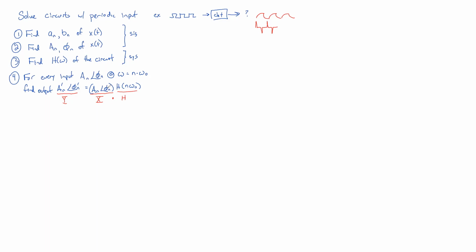So this is going to be a complex number. This will be a complex number. Multiply them together, we'll get a complex phasor output. And now that you've done that for every single frequency, you can now synthesize your output. It'll be equal to your fundamental plus the infinite sum we covered in the other page, which is our magnitudes and phase offsets.